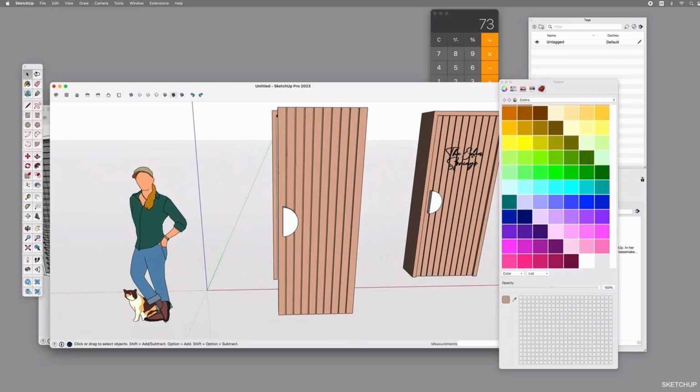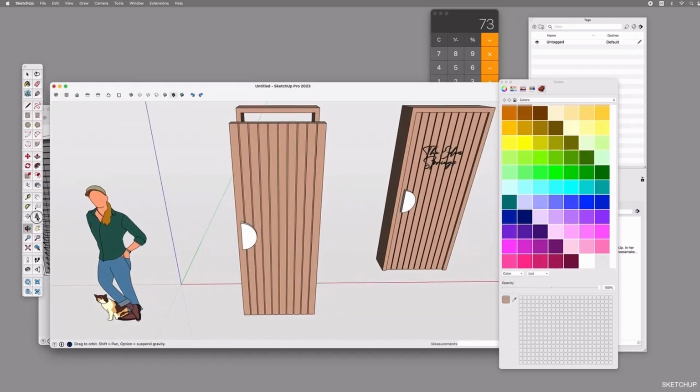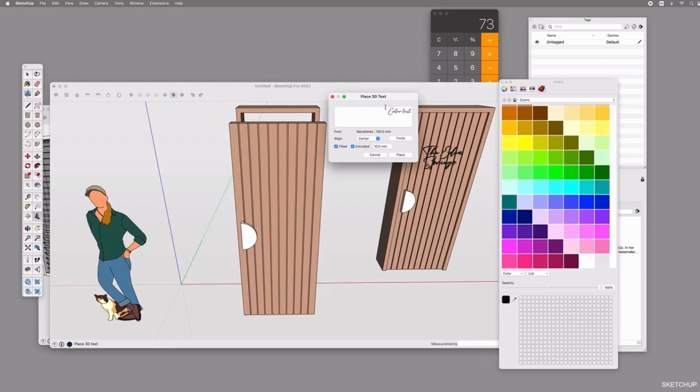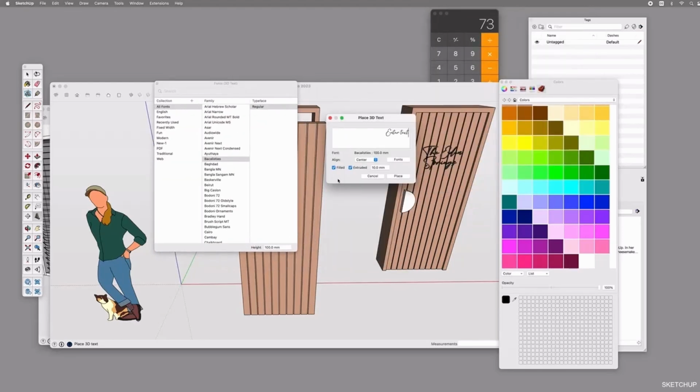Now let's create the handwritten letters to make it super fancy and Insta-worthy. But of course, I want to show you how to create extruded text mainly. Click on the text tool and open the font section. We will need it in just a second. Choose how wide you want your text to stick out. Then, I'm not sure if this is a SketchUp 2023 bug, but for some reason, right and center alignment are exchanged.